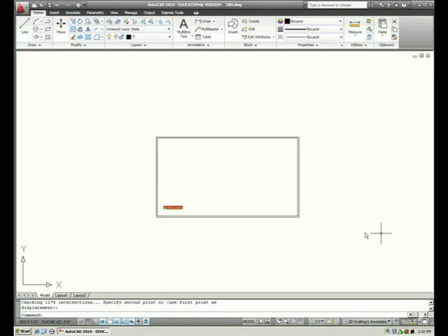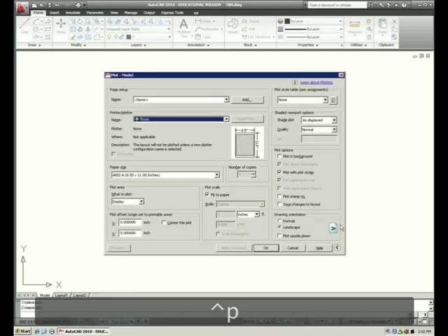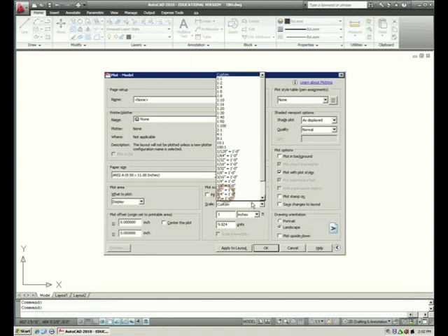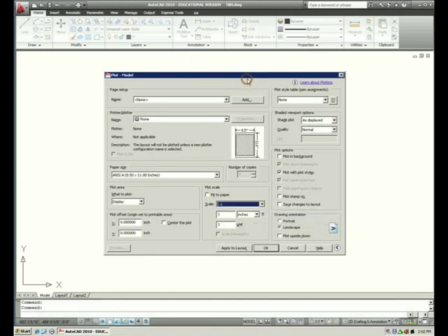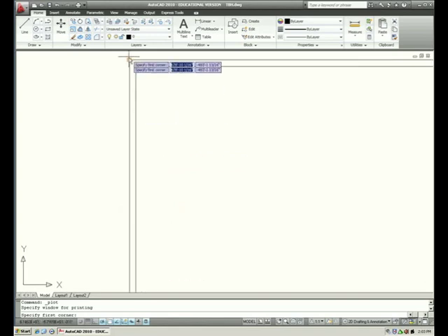Before you plot, you will have to choose a plot scale equal to true size now, which would be 1:1, because you technically already scaled the drawing down by a 64th inch scale factor. Select a window for the plot area, and then select the perimeter of the reference lines.